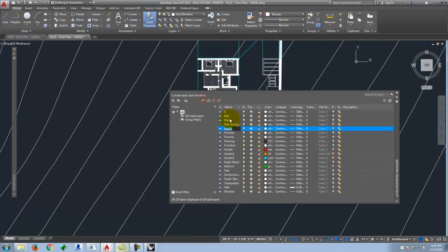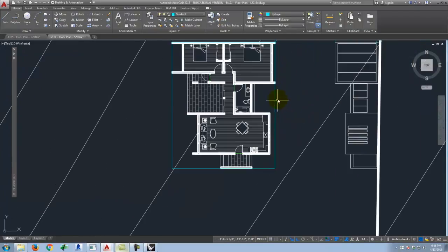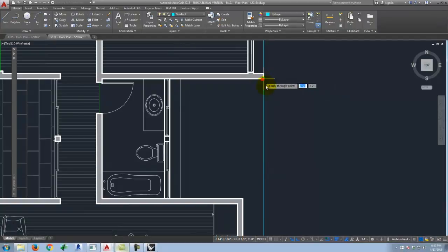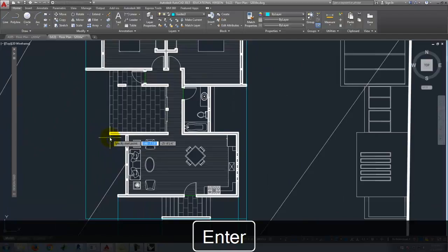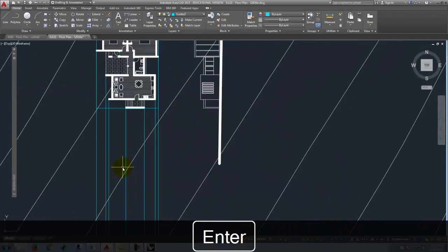So we'll create a new layer called west elevation. And I'm just going to use the same guides, the guides 3 layer, because they're on the opposite side. I don't think it'll be too confusing. So I'm going to go ahead and pull my points just as I did before. So I'll do a ray from this corner, going in that direction, from this corner, going in that direction, from this corner, that corner, that corner, that corner, and that corner. So again, I'm starting with just those corners.